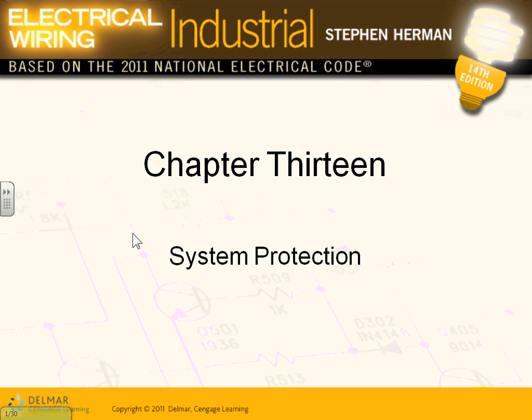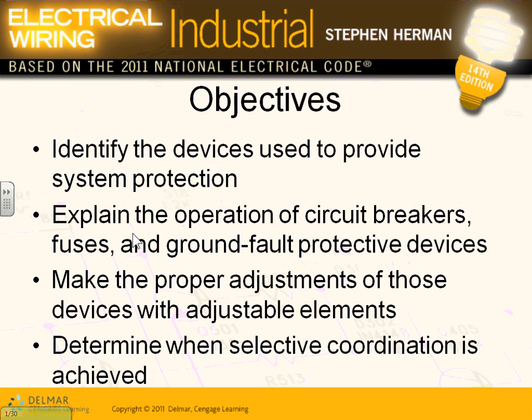We care less at this point about the frequency, because the frequency on the low voltage is not an issue. For the most part, the frequency is constant from the utilities. The voltage, for the most part, is constant. You can correct it with power factor correction. Directional overcurrent protection device coordination is not an issue in the low voltage. It becomes an issue in the high voltage. So focus on the overcurrent protection device. That's what we're going to do.